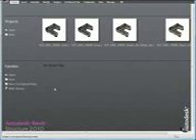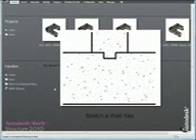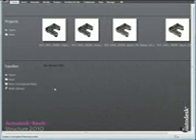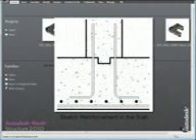In this lesson, you will use the drawing tools provided with Revit Structure to add wall keys to the footing and sketch reinforcement in the slab foundation. The reinforcement will include both parallel and perpendicular rebar that extend from the concrete slab into the structural wall.